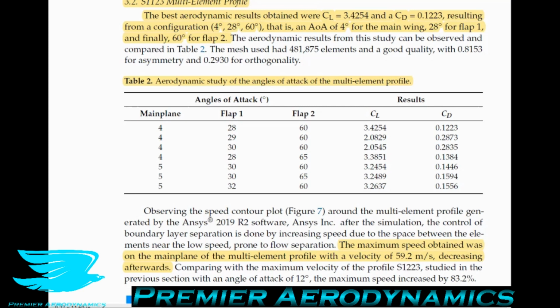It means that if you're driving your little Formula Student car around and upstream you have another car, its wake will dramatically affect your drag or your downforce production at the moment, because the wake is going to hit your wings and it's going to destabilize the flow a lot. It shows that just a small change in angle of attack has a massive reduction. It's like about a 30-40% reduction in lift. So that's not good. However, at other angles of attack, the system seems to be a lot more stable.